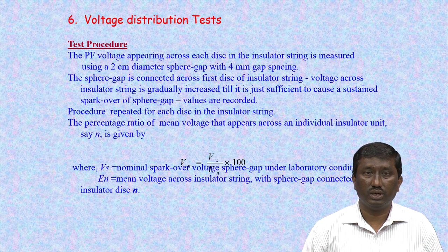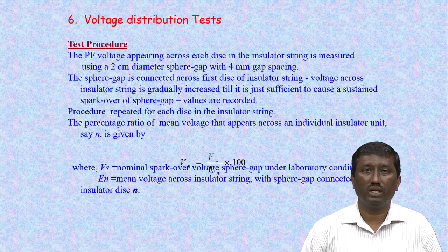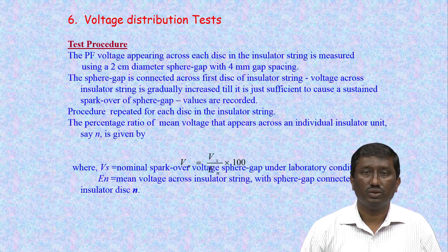the ceramic disc insulators are connected in cascade in the transmission lines, whether it is an I suspension, a double tension or a V suspension string. We know that for 400 kV we have anywhere between 23 to 25 insulators cascaded. Similarly, for 765 kV we saw 35 to 40 insulators in cascade. These insulators typically have a capacitance ranging from 40 to 60 pF for each disc. Connected in cascade, the voltage distribution from the line end up to the ground end has to be